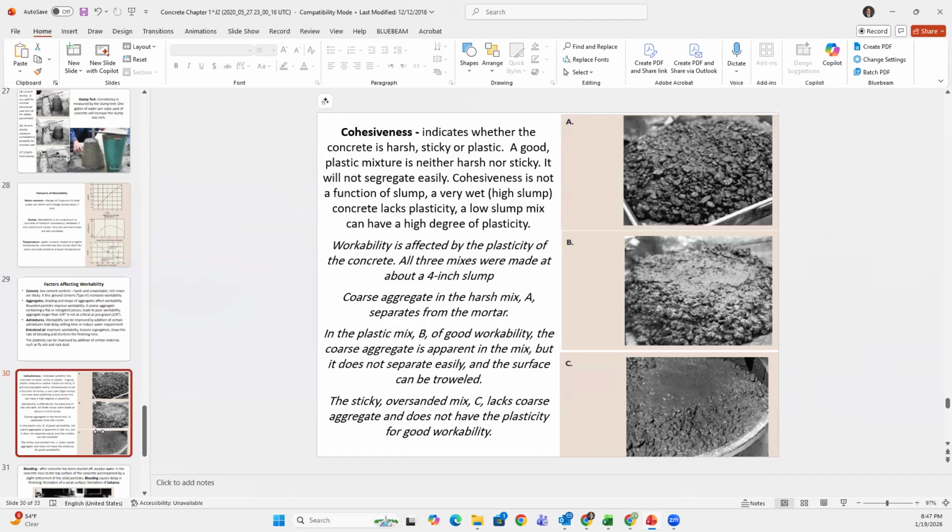So basically, workability, as Matt said, should not be misunderstood with strength. You always want strength, but it's different when you use a slab on grade or a driveway versus a high-rise floor slab.